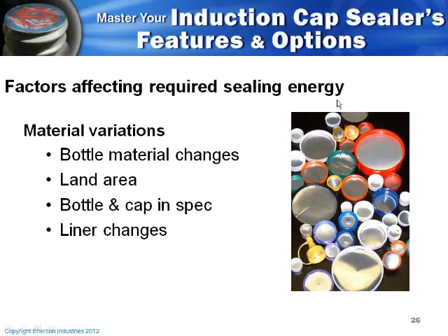Another piece you're going to want to look at is the specification for your bottle and cap. You want to make sure that those are consistently within spec. We typically recommend taking random samples and just verifying they're in spec. We have seen cases where one of the two was out of spec. The packager got a seal, but it ultimately wasn't as good of a seal as they would have liked to have seen.